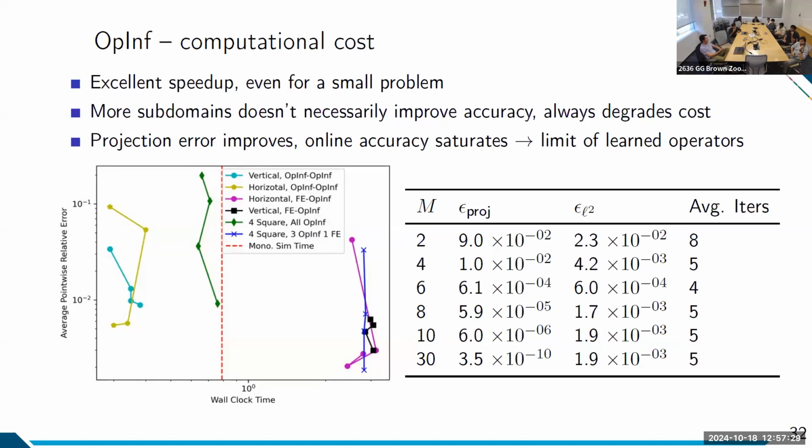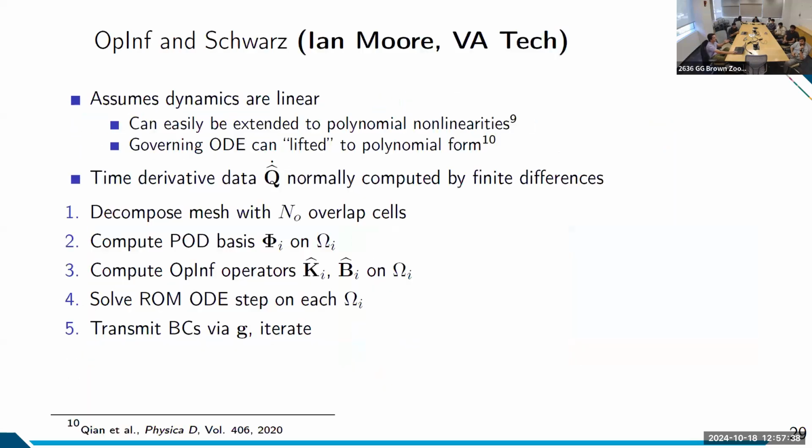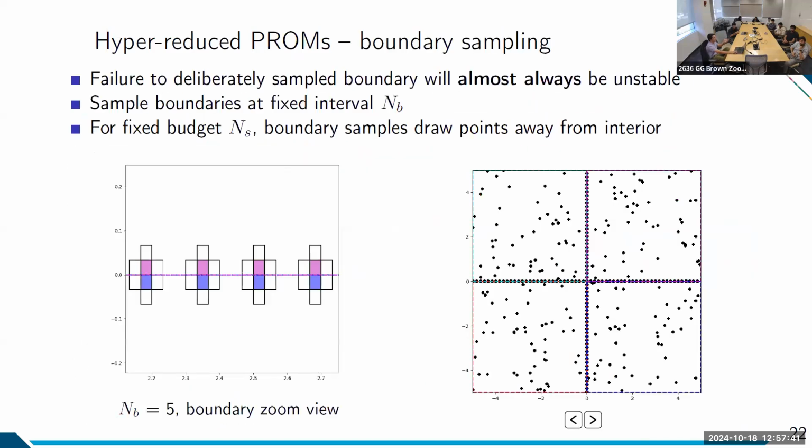Okay. And so those can factor in. If you only have a few points, like thermocouples at a few points, maybe that is what you're choosing for your boundary sample points, and you're transmitting boundary conditions only at those few points. For those reentry vehicles, say you have thermocouple measurements from the ablating heat shield, but then you simulate your fluid flow system. You would select points in your fluid flow system that correspond to where your thermocouples are, and then just feed that in as a boundary condition from your experimental data.